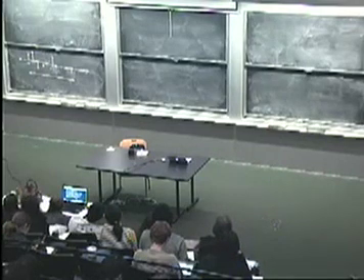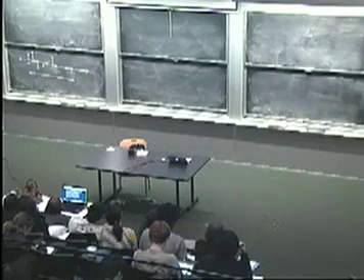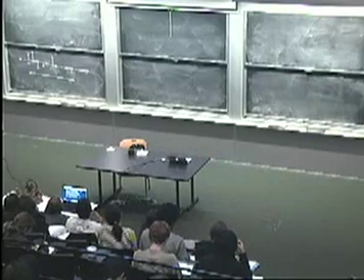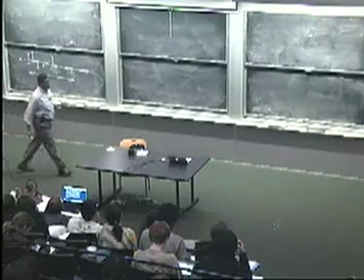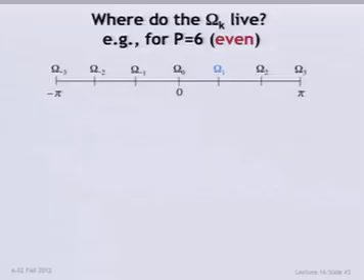All right? And the nice thing is it turns out that you can actually recover the time domain signals from the samples of the DTFT through the formula on the right side. So what we're doing is we're actually computing the DTFT just at isolated points on the axis between minus pi and pi, just P, capital P points.